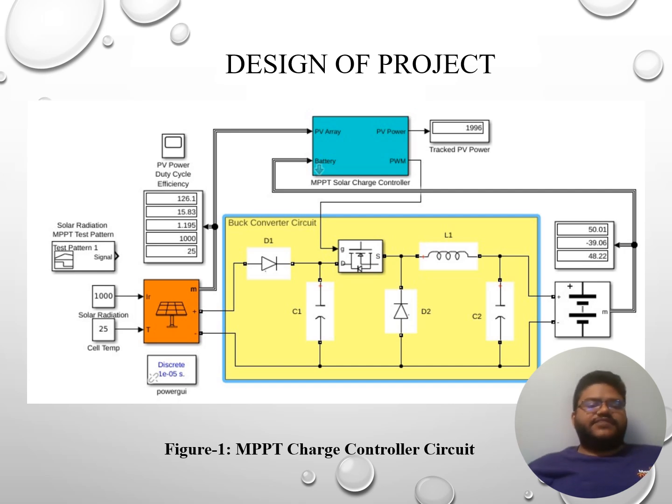So this is our design. We can see the solar panel here, the PV, where the sunlight gets exposed, and this flows through the circuit. Ultimately, this solar energy is converted to the voltage output. Here we can see the reading that we get for the final voltage, and many basic components are used in this circuit, like the diode. There's a MOSFET, which is acting as a switching device. The diode only allows current to flow in one direction, and the PV is responsible for converting the sunlight's energy into electrical energy.